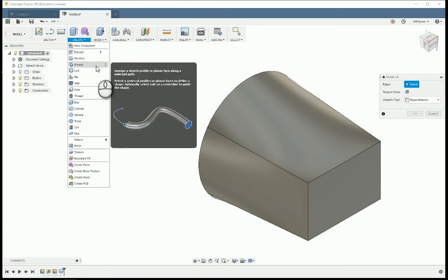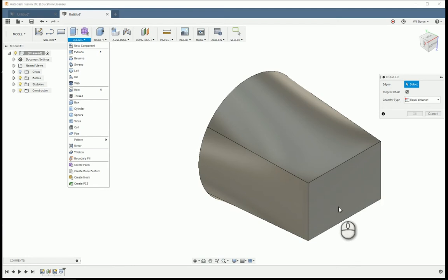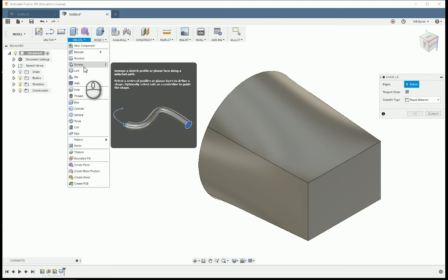Sweep tool is pretty fun. If you draw a 2D object, for instance a square or a circle, and make a spline line, which is that organic line between the two, you can sweep along a profile. So it follows a shape along whatever path you specify, with a straight or curved line. For fingers especially, that's how I've told people to make fingers. You draw your circle, you draw the path that you want it to follow in 3D space, and then you just use the sweep tool to follow along that curve.